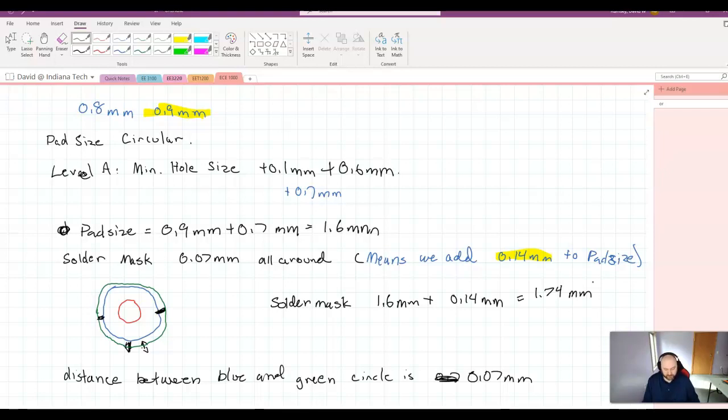It has to do with the fact that Cadence basically does everything in inches, and so when you save in millimeters, there's a quote loss of accuracy because it's doing a conversion back and forth. So I think it's still saving the data in inches, and then when it's opening back up, it's converting the inches back into millimeters. And that's where this loss of accuracy is coming from.